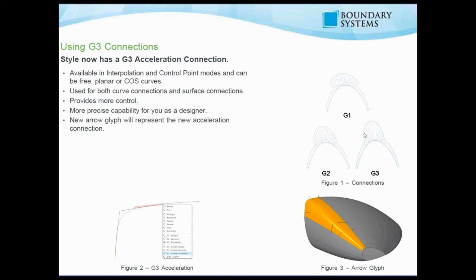Okay, next, again about Freestyle. So now you can import and export OBJ files directly into or out of Freestyle. So previously, you could import OBJ files, but they would come into Creo Parametric and you couldn't manipulate them with Freestyle. So now that you can import those directly into Freestyle, it allows you to leverage the control mesh that was in the OBJ previously.